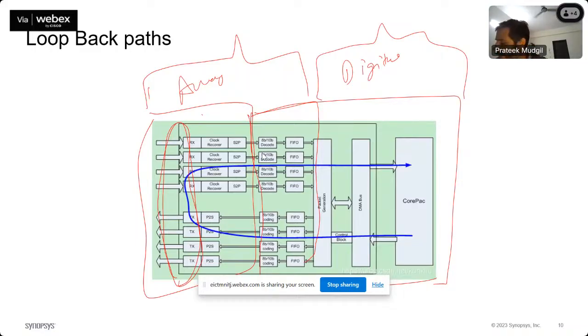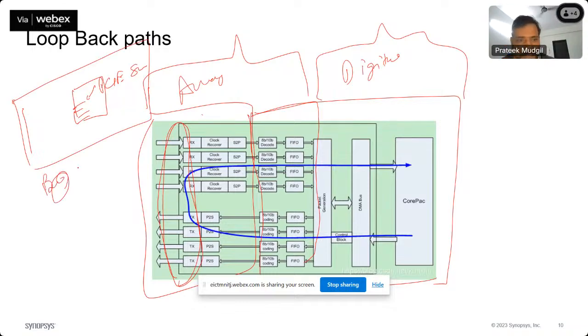So now let us say we have an SoC and we have PCI slots or DDR slots, and silicon comes and we put it on the board, and then we see that our PCI is not working or DDR is not working at all. You see these are the analog blocks. In these blocks we can't have ATPG and scan options, because these are majorly analog blocks. Inside those blocks we can place a digital block and put some ATPG, but majorly these are analog blocks that don't allow scan chains inside themselves.